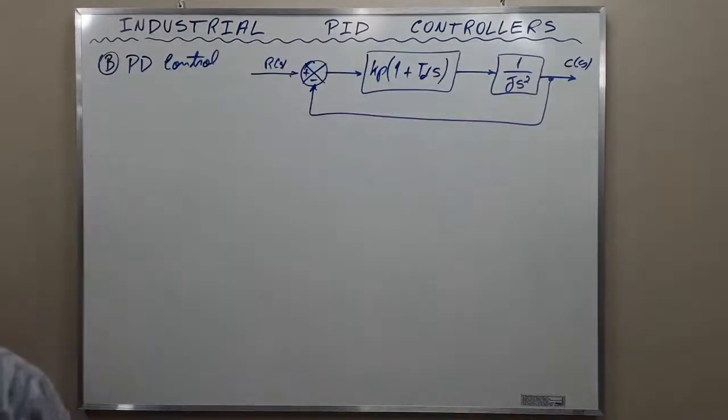Let's observe the purpose of a proportional plus derivative controller. The derivative control is essentially anticipatory. It measures the instantaneous error velocity, predicts the large overshoot ahead of time, and produces an appropriate counteraction before too large an overshoot occurs. Consider the system of the figure.